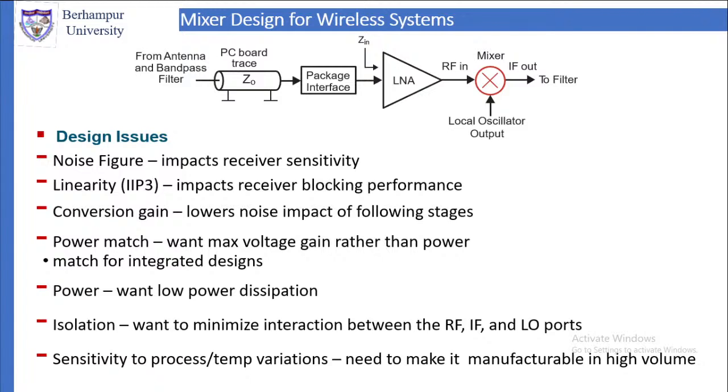So if you are doing the LNA and the mixer together, then the input impedance of the LNA is the input impedance of the total circuit. The input impedance of the LNA is matched to the antenna, and that is for maximum power transfer. Now in designing the mixer for integrating it to the LNA, there are some design issues.